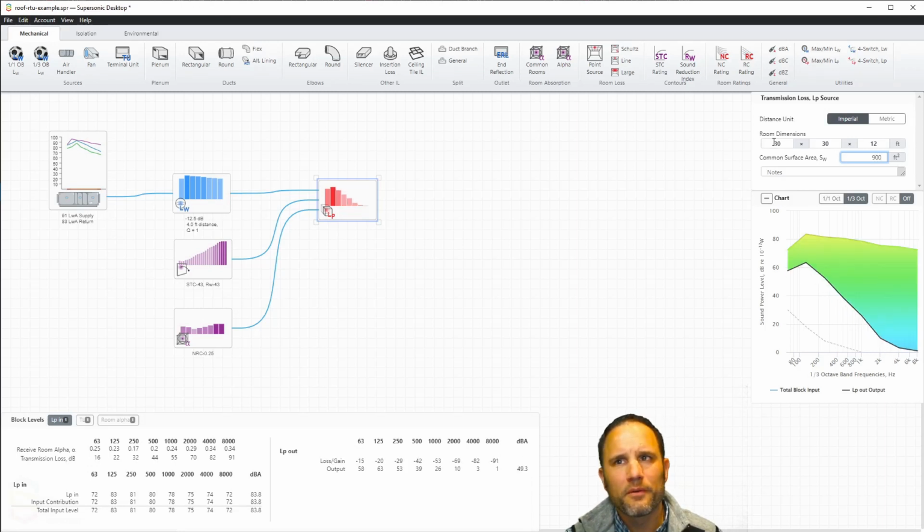Now remember, this is a rooftop, and the sound level is dissipating as we move further away from the front edge of the classroom to the rear edge of the classroom. So we need to interpret a little bit what the source level is across the roof as we get further away, given that from 4 feet you get some significant doubling across that 30-foot classroom span.